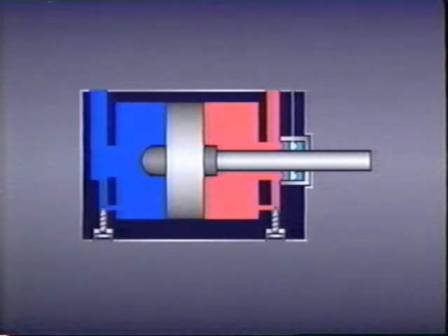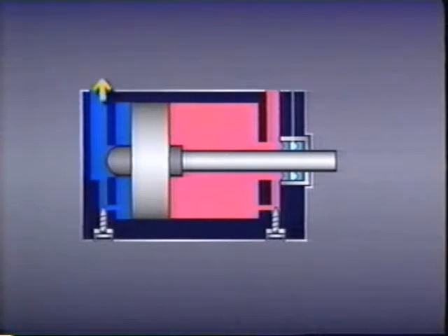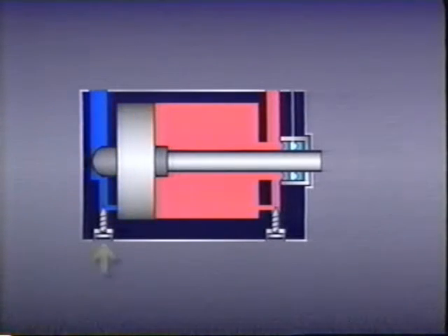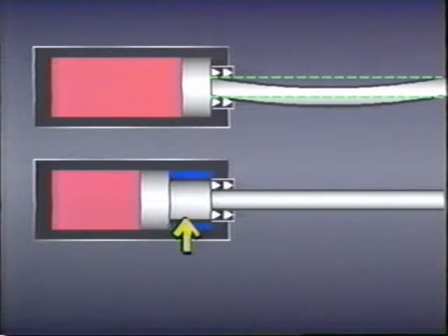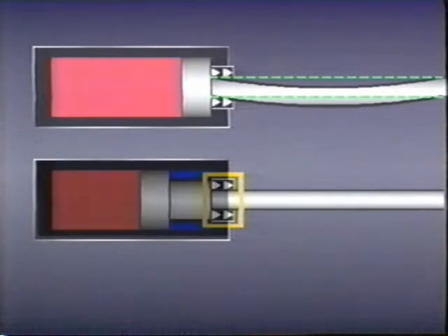As the piston nears the end of its stroke, the spear blocks the opening, forcing the fluid left in this area out past the needle valve. Adjustments of the needle valve determine the extent of the cushioning action. Sometimes stop tubes are installed in cylinders to help provide support for long piston rods. The tube helps minimize damage to the rod gland and to the inside of the cylinder body.